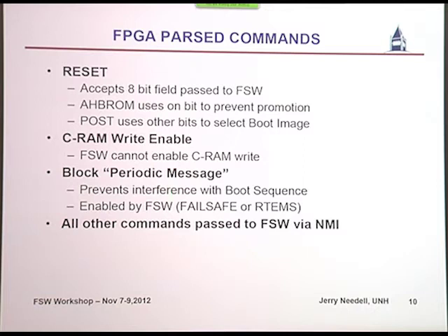And again, I'll get into a little later, but having a command come in while we're in the process of booting can be highly disruptive. And so the FPGA does allow us to do things like block certain commands while we're in the boot process. I'll talk a little more about that later. And the other commands are passed directly to the flight software through a non-maskable interrupt.